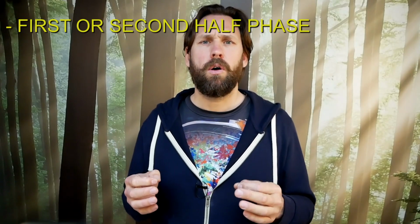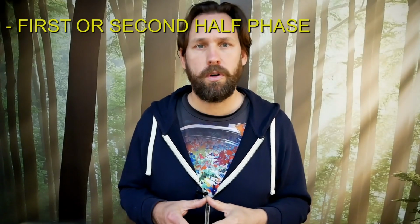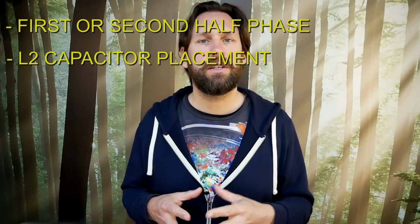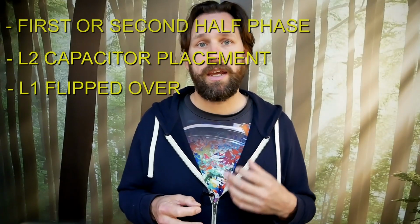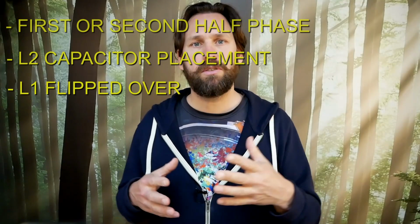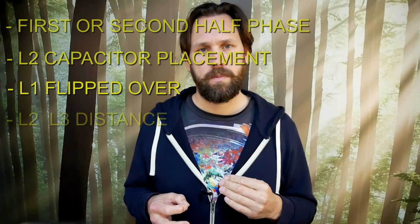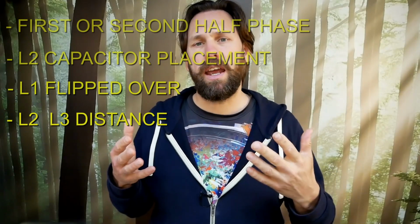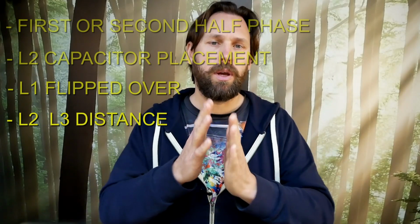I now have shown you how to place the impulses of L1 onto the first or second half of the series resonant wave of the L2 coil by changing where the series tuning capacitor of L2 is connected to the MOSFET switch. I also explained that L1 needs to be flipped over when the L2 series tuning capacitor is connected to the MOSFET source. After that, I have shown you the impulses then can be fine-tuned to the current maximum by changing the distance between L2 and L3.